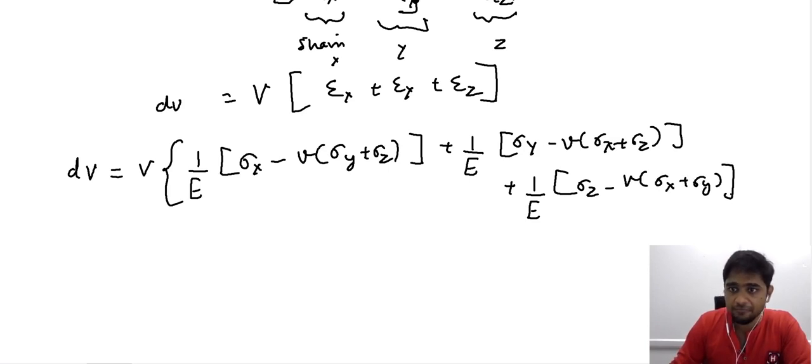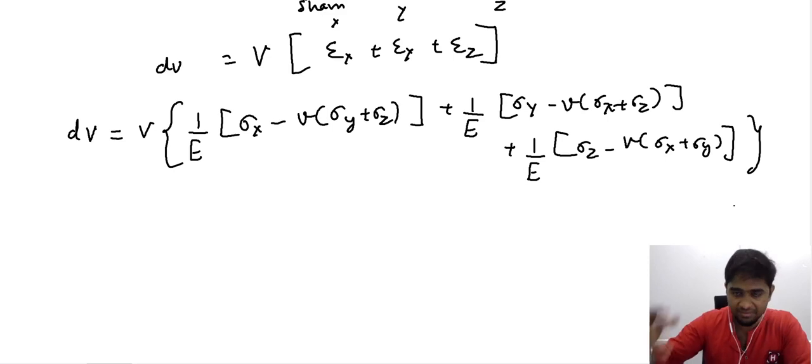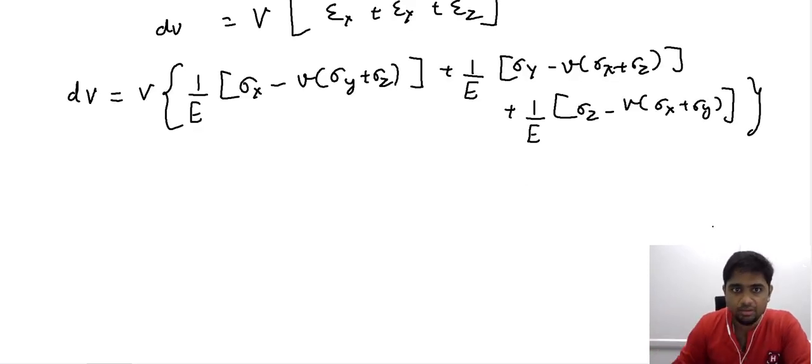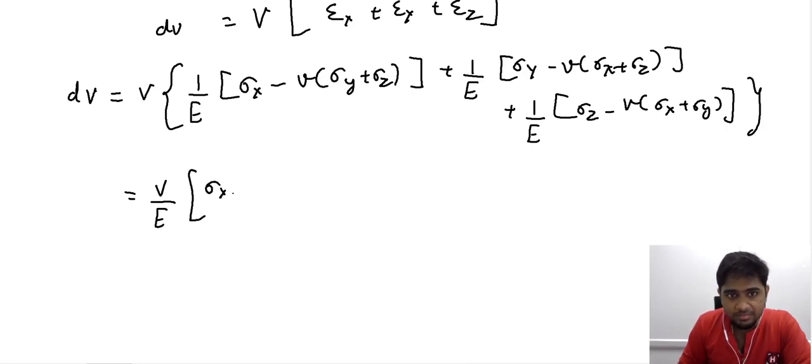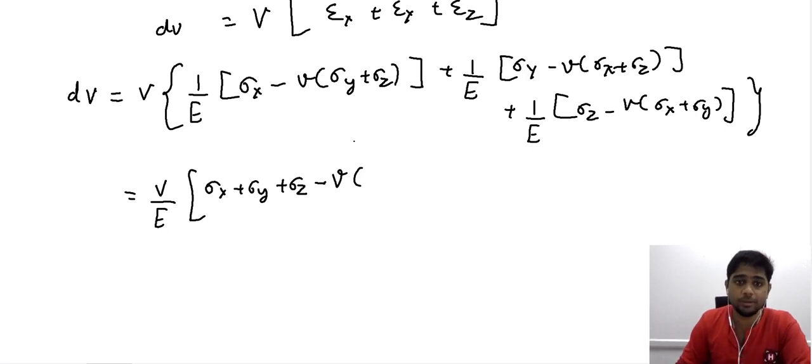Again, we have considered the form of these individual stresses earlier, even in this lecture. So there are common terms. This E, the Young's modulus, is a common term. So nu by E, and it is also possible for us to rearrange. Once you take the E out, we will be able to sum these sigma x, sigma y, and sigma z separately, and we can take the Poisson's effect also. So when you take the Poisson's ratio, nu, out, you would end up having these combinations of terms.